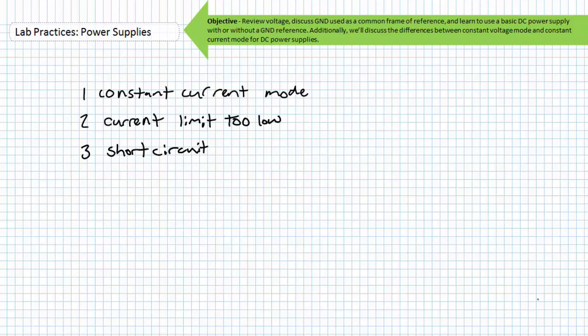Again, ordinarily power supplies are operated in constant voltage mode under the current limitation. Constant current mode is typically just employed as a backup. As a bit of advice, check the power supply output voltage for every load configuration and don't just assume its output stays constant. Realize output voltage could vary widely between unloaded and heavily loaded conditions, for reasons I'll explain when we get to the series DC circuits lectures. The analog needle meter is there just to get us in the right ballpark. Always use your DMM in voltmeter mode to verify output voltage for loaded conditions and readjust as necessary.